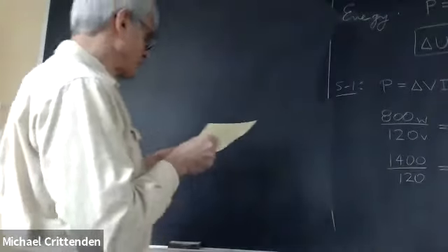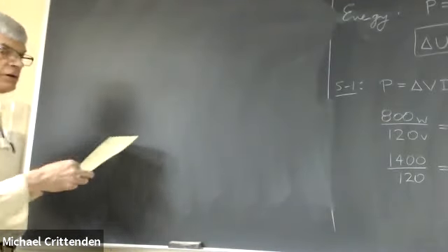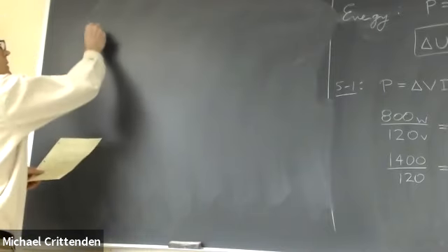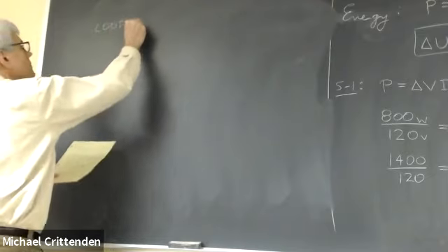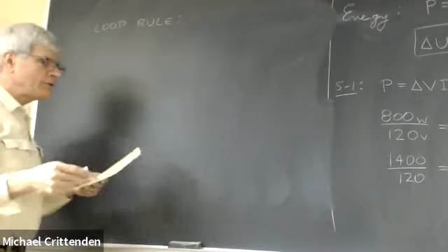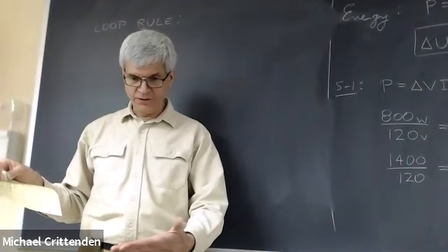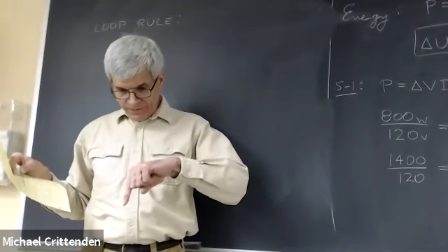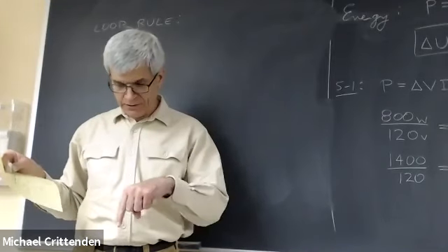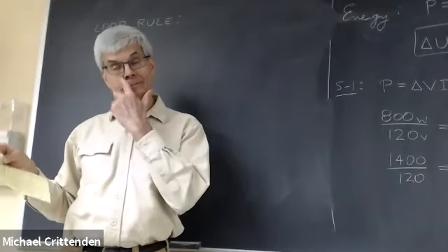Anyhow, there are two expressions, and I've got just enough time to get them written down, and then we'll actually use them for something next time. First of all, there's the loop rule. If you have some elaborate circuit on a piece of paper in front of you, some sort of wiring diagram, and you start following wires around some path along that wiring diagram, and eventually you end up back at your starting point.